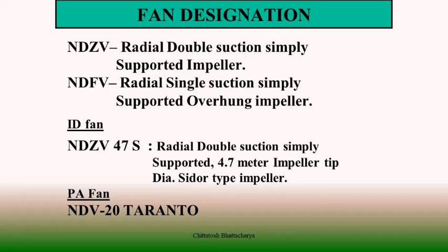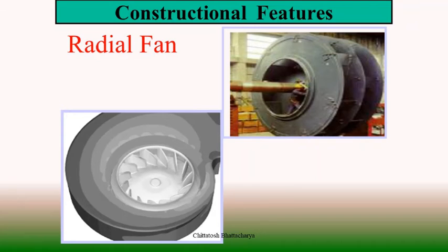This shaft is fixed with the impeller rotor in the hub position, and they are either riveted or welded. Mostly they are found with a riveting type of bolting arrangement, and the arrangement is covered in such a way that there is no erosion effect of loosening, and the shaft is fitted with the rotor through a key arrangement. Key slot is there, so that way they are connected.